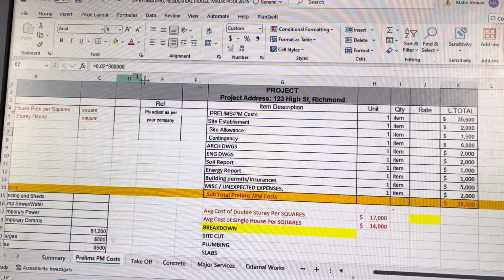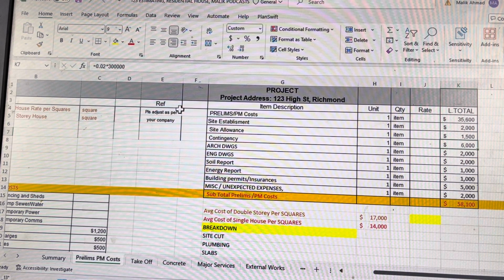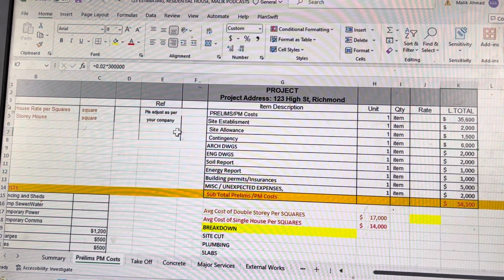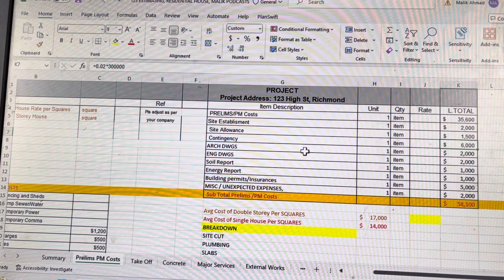Contingency: generally if the project cost is say $300,000 or $500,000 or more or less, you want to put some money in as contingency. That's generally 2% or 5% contingency, which should cover all human errors and other unexpected expenses, surprises, heat off, rain off, some other costs which you didn't allow in the estimate. Because you're living in a real, practical world, things do happen and we come across such things, and that is the cost. So that contingency will cover that.